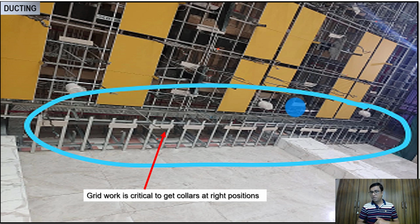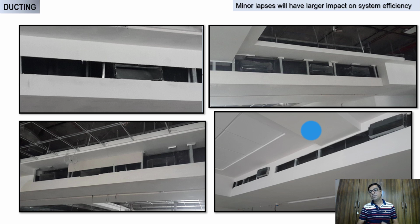As I said, grid work is very, very important, and this is one of the good examples of getting the grid works. We can see all these where the collars can be properly terminated. Otherwise, there will be loss of air. Otherwise, you can see the bad part of it. Look at the grid work and the kind of collar. They are sometimes out, sometimes in, and there is no proper workmanship. It's total chaos. I don't blame only the workman; the supervisors who are carrying out that job are equally responsible.